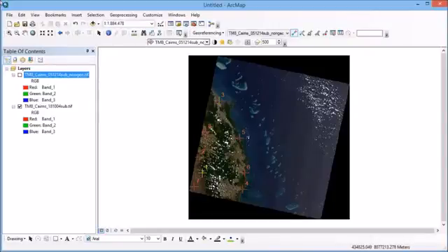Now this particular image is rather challenging because what I really want to do is to get those stable ground control points, and I can find several of them easily enough on the land area, but certainly in the water area that's really challenging, and even in parts of the reef, if there's no exposed land, that's really difficult as well. But what I'm doing here is just for demonstration purposes, so you can get the idea of what's required.